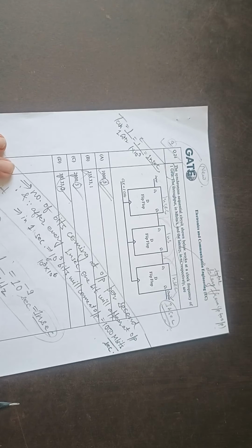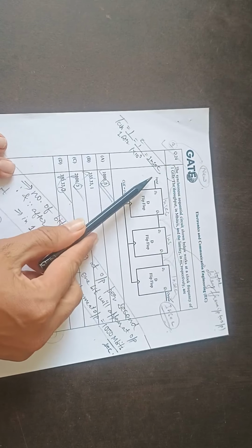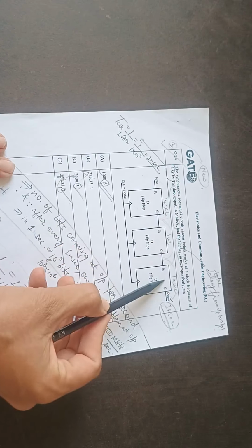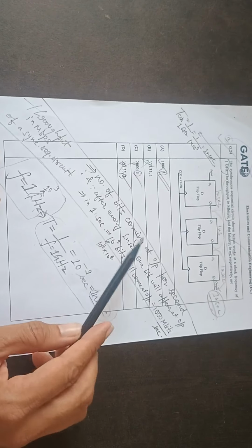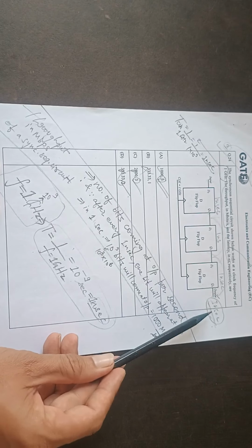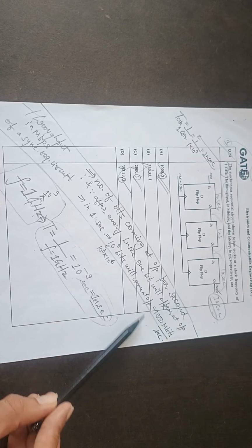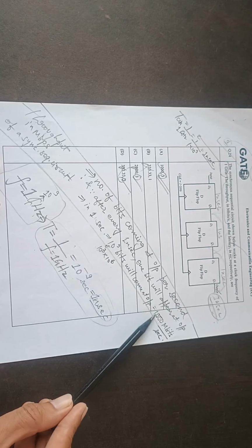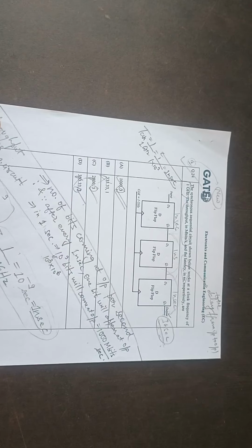Okay. So clock frequency we have found out is 1 nanosecond. So after every 1 nanosecond, one bit will move. So this is 3 nanosecond, and therefore latency is 3 nanosecond, and throughput is the number of bits that will come, like after every 1 nanosecond one bit will come. So in 1 second 10 to the power 9 bits will come, so it is 1000 into 10 to the power 6, so 1000 megabits per second is the throughput. Okay.